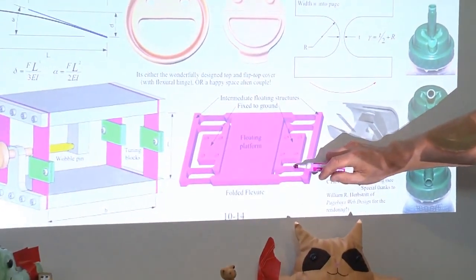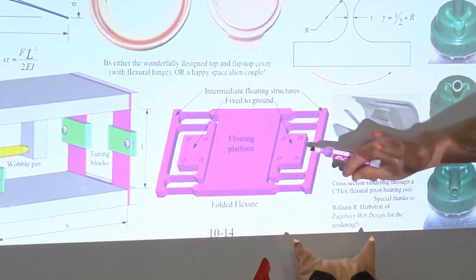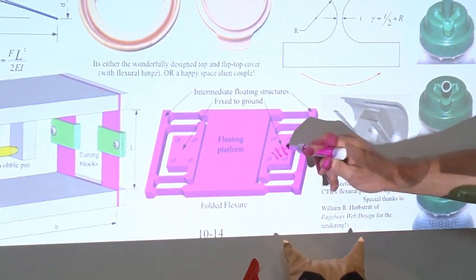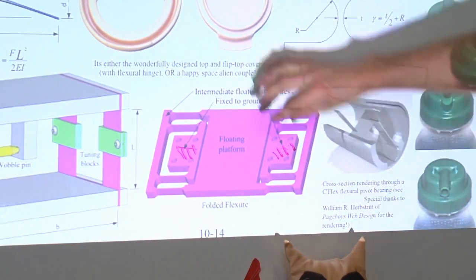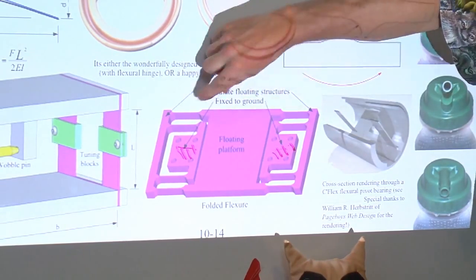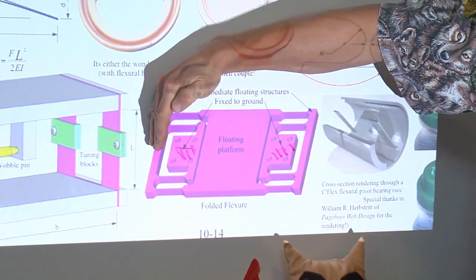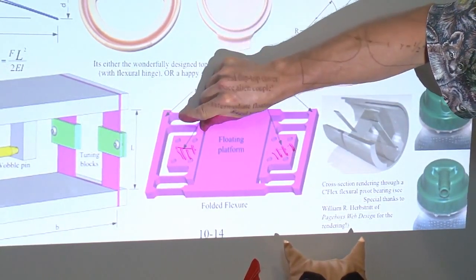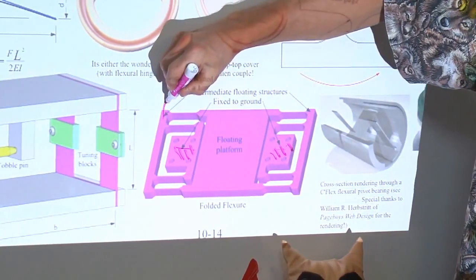where we have these flexural linkages, if this structure here is anchored to ground, and when this platform moves, this beam bends and wants to get shorter, dragging this structure in. But when this beam bends to ground, it also wants to get shorter. So this side moves inward.